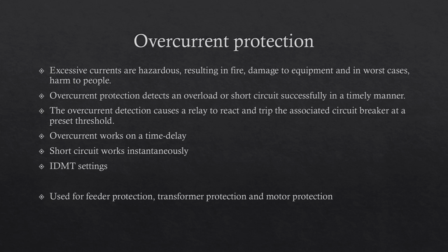And what this is, is an ability to sense an excessive current, whether it's a short circuit or an overload, and be able to, in a timely manner, disconnect the circuit from which the overcurrent is occurring and prevent fire and damage to equipment, or even in the worst cases, harm to people, which will take the most precedence naturally.